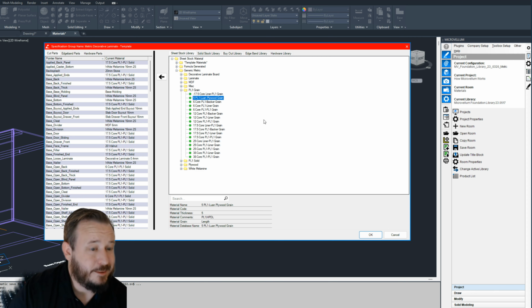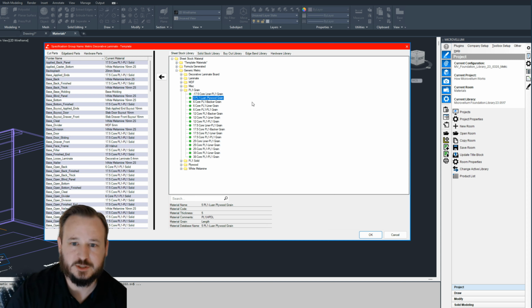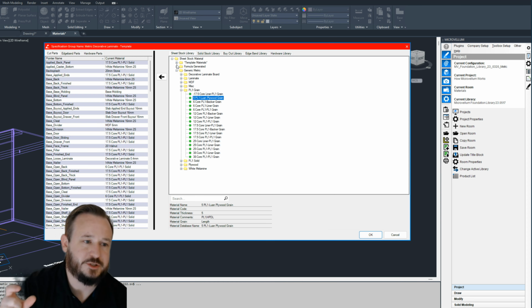So for shops that have a common material name set up and pointers assigned, but need to be able to edit the thickness, you can set those up to be clonable so that when you create a new project and it automatically creates those project spec groups, you now have all project level materials of exactly what you need already assigned to your pointers.